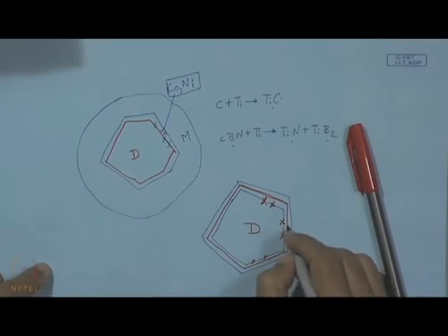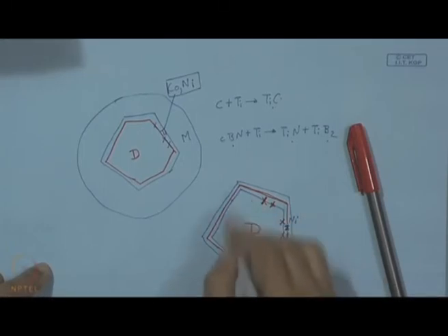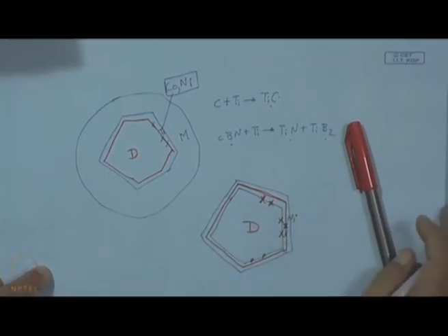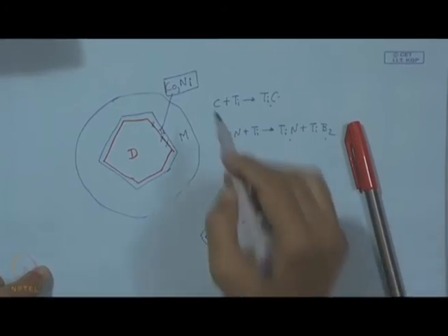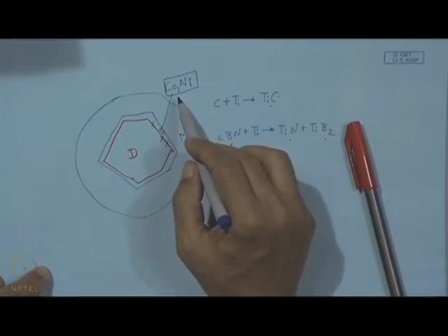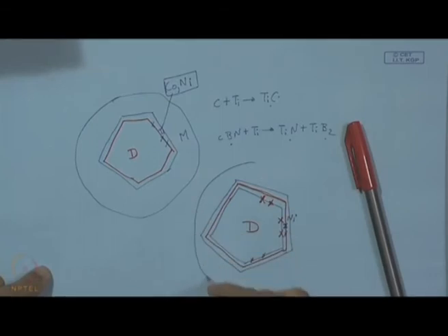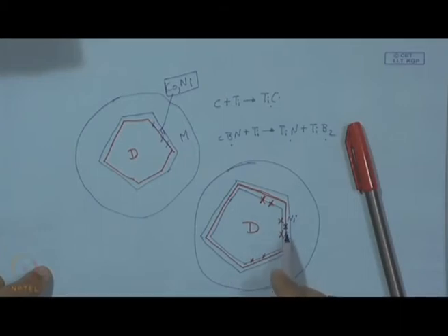So, we have two coatings here, the interface between this is nickel coating. So, this is the interface between titanium coating and nickel, outer surface is nickel. So, titanium is totally protected, covered, it is shielded by nickel, and this nickel is not so easily oxidized. So, conventional metals which are not very reactive can have very easy bond formation over this outer surface of diamond, which is now just a coating of nickel.